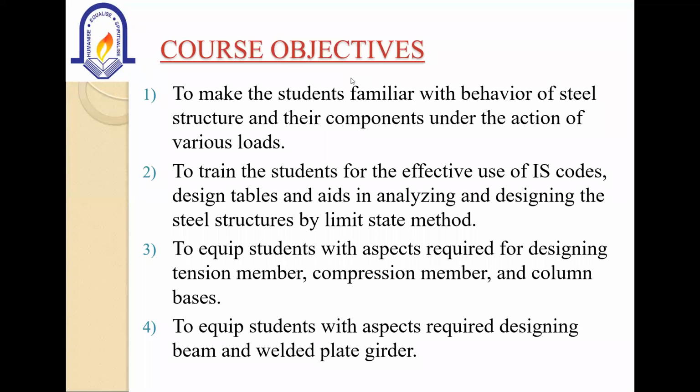So the first important load is the dead load. So what do you mean by dead load? Dead load is nothing but the self weight of any of the structure. Then comes up the live load. So live load will include the furnitures as well as the other things that you are going to put on the structure, that will be included in the live load, as well as the human beings that are also considered as a live load only.